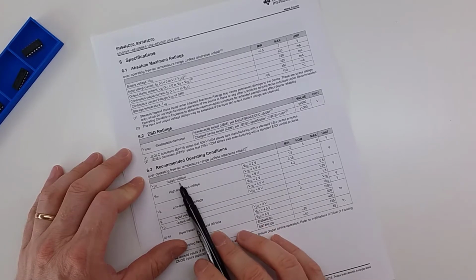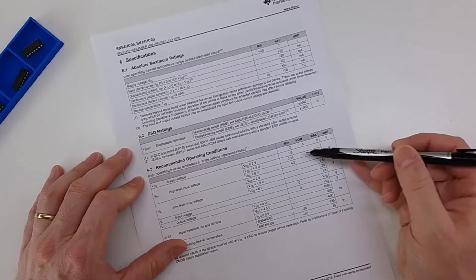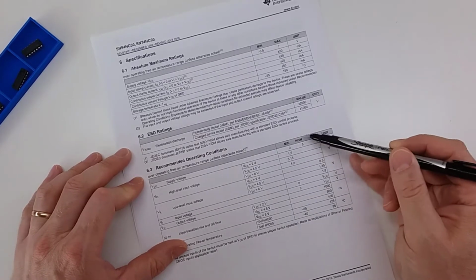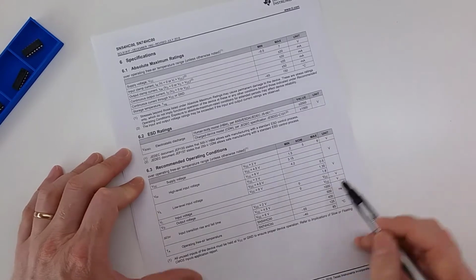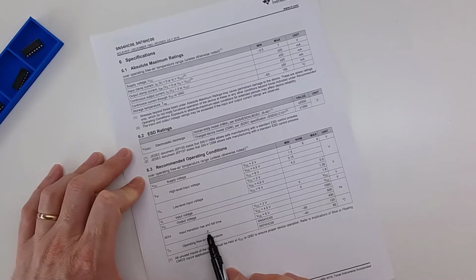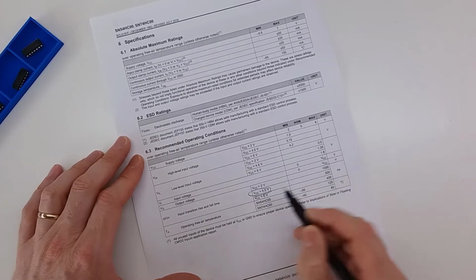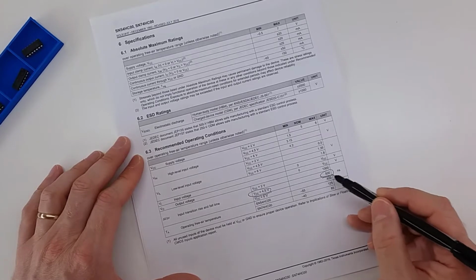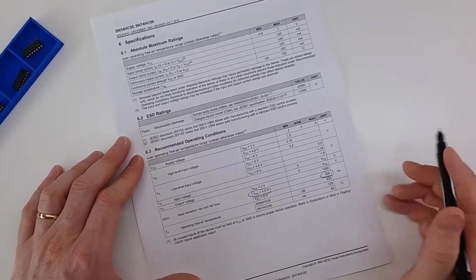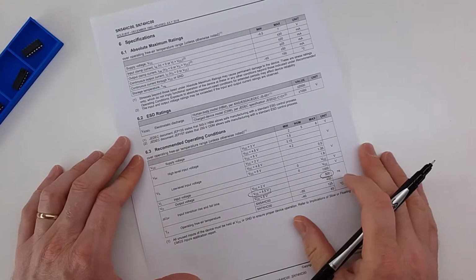But this one has a recommended supply voltage of 2 to 6, nominally at 5. This was kind of designed about the time where a lot of controller boards were running off of 5 volts. And one of the other things you'll notice right here is this input transition rise and fall time, and we're going to be operating it at about 5 volts. So we'll look at about here at 500 nanoseconds. And so we'll see if this can hold up at about 500 nanoseconds on the oscilloscope, and we'll see how that waveform looks.